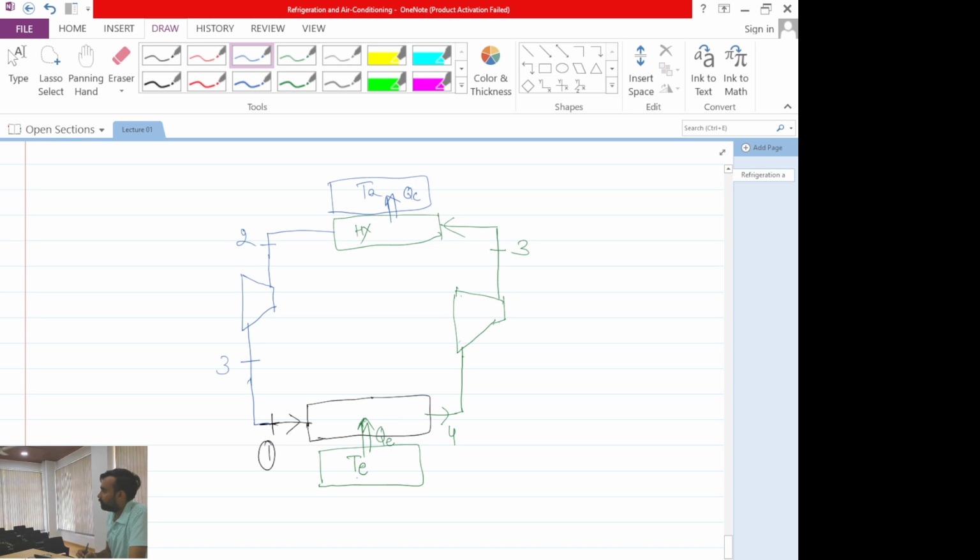So, what do I need to do here, please tell me. Here, the liquid plus vapor mixture is changing from low quality to high quality. It means that liquid is converting into vapor. Evaporation process is taking place. So we call this heat exchanger nothing but an evaporator.